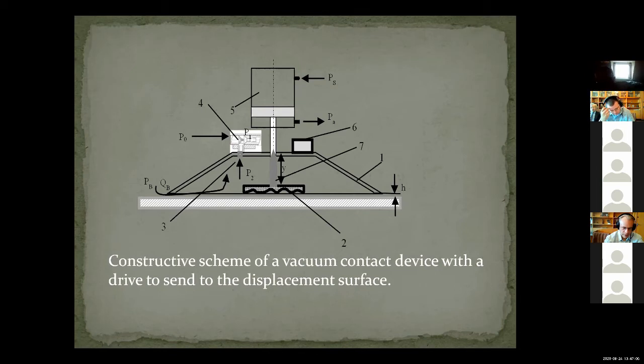Pressures PS and PA are formed by the control system and are intended for plunger motion up and down. Vacuum generator 4 is intended for creation of absolute pressure P2. Environment pressure PB depends on the underwater wall climbing robot depth in water. In the air, PB equals PA, since it is atmospheric pressure; the output channel of the vacuum generator is removed from water and connected with the environment.